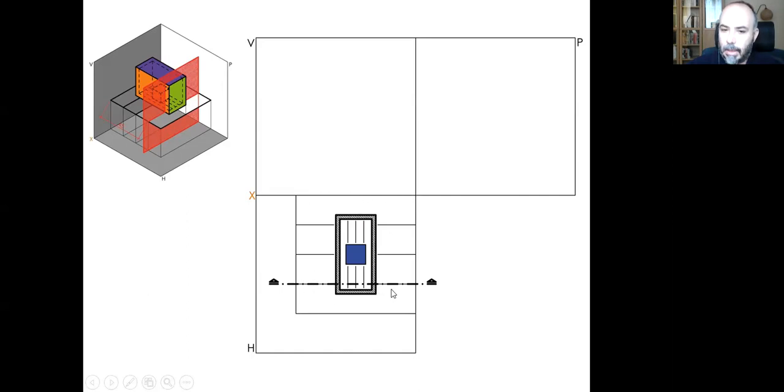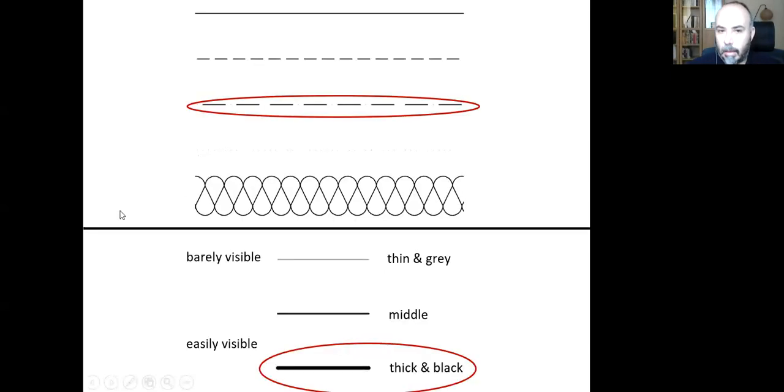And just to indicate that this is a cutting plane, a cutting surface, I am going to use a new line type. Here, this one I should use. If you see something like this, a dashed line with points placed at the gaps, and they all should be as equal as you can with your eye, without measuring it with a ruler.